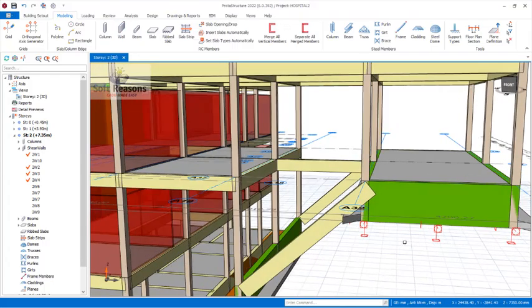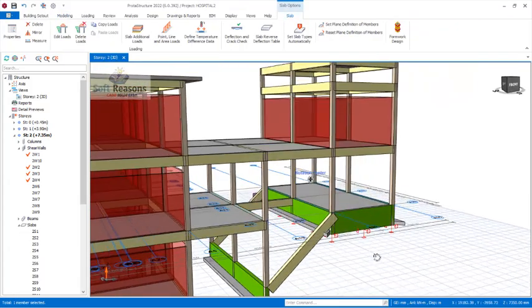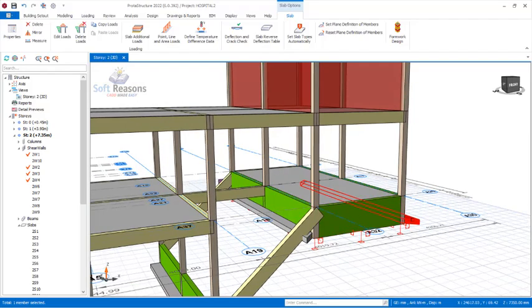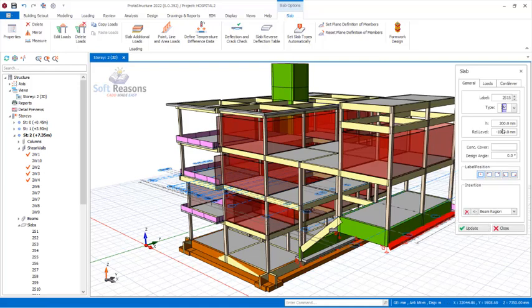Coming to the slab, the slab that will serve as a support to the foundations. What you need to do is get to your slab right there. For instance, if you select this one, right click and then click on property, you can notice the setting. You can see the relative level right there is -1000. -1000 simply means you are sending this slab downward by 1000. You are sending it downward 1000, and the slab type is a cantilever slab.